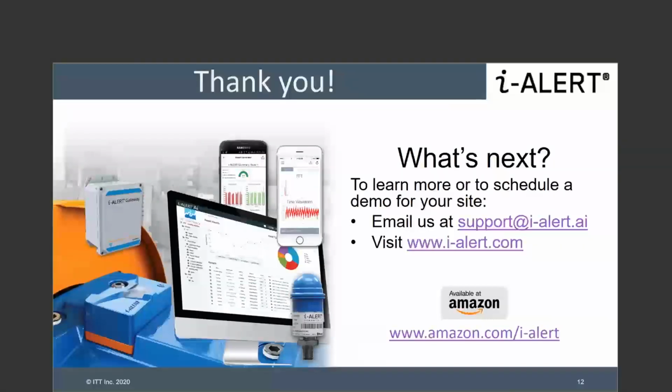Yeah, correct. We have a special magnet that we sell that goes with the device and works very well with the device. What Troy's referring to is we have a Hall effect sensor that essentially is used to shut the iAlert off and put it in various states of sleep mode that exists in the device. So if you get a magnet too close to it, a strong enough magnet, and we've reduced the sensitivity of that Hall effect switch so that now it takes a much stronger magnet to shut it down.